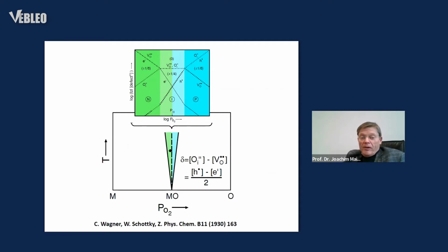So this is a typical phase in the phase diagram. Let's take an oxide, maybe zinc oxide in between zinc and oxygen. And this is not a line phase. You have a certain range of stoichiometry. You have deviations from that one-to-one composition. Maybe very small, maybe not even variable. But what happens when you go through it, and you can go through it by changing the oxygen partial pressure over it,